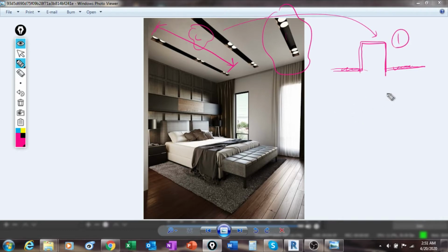Now the second family is going to be a regular lighting fixture. Okay, so I guess we're gonna do a regular lighting fixture. It doesn't have to be a ceiling based lighting fixture. It can be a regular one, and then we're gonna bring it into this family. And once we bring it in, we're gonna make sure that this lighting fixture family is locked in place. So when I change the length of my case, in any project, my lights remain in the same position.